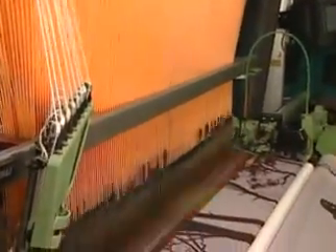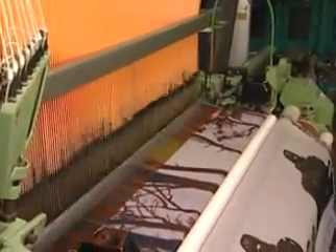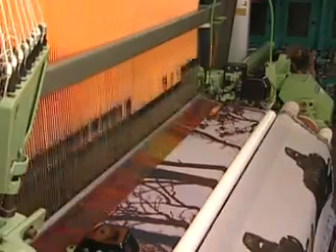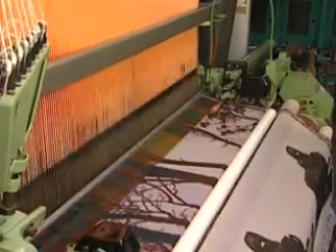Up to 12,000 warp ends can be controlled. These systems can employ mechanical or electronic devices to actuate the warp ends. Design capability is virtually unlimited. Pattern areas can equal the width of the fabric and are almost unlimited in length. Fabrics made on jacquard looms are normally more expensive because of their complexity and slower weaving speed.